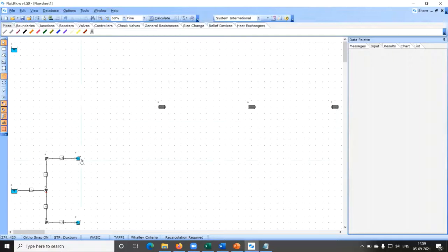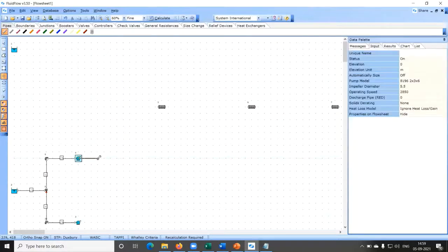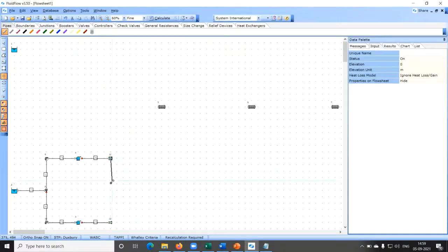In the pump discharge side also, we'll have the mirror image. So from the pump, I'll start, click from the other pump, another line, click from open pipe to open pipe, which will become a bend. From the bend, I'll go to the right, which will be in the same column as the first exchanger. Okay, once it is done, please type done.